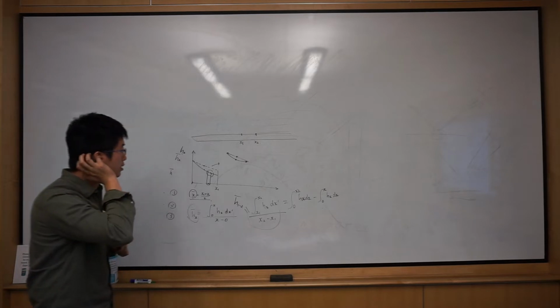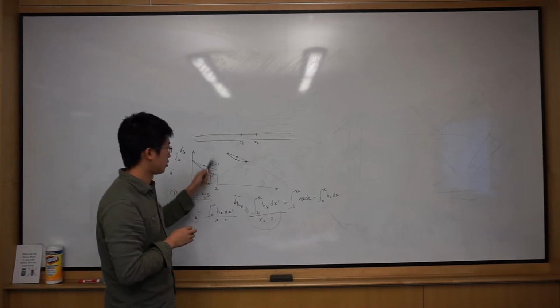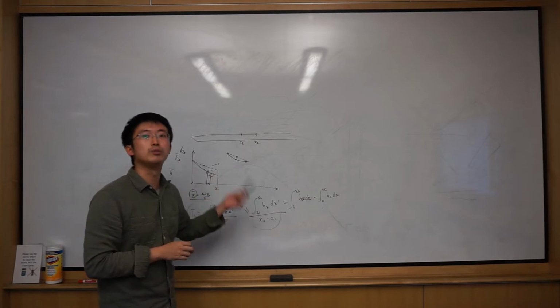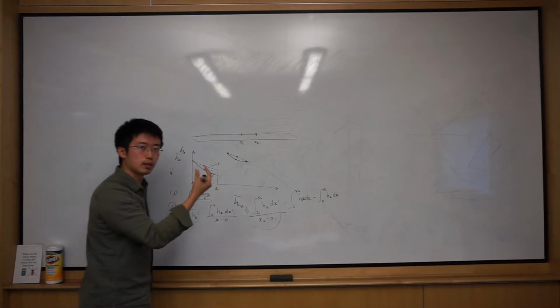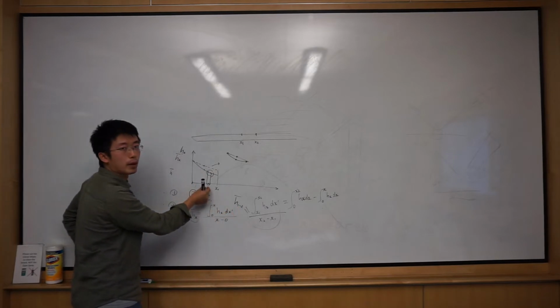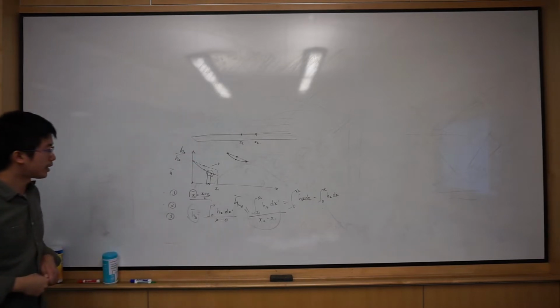So it only works if the convection coefficient function, the curve of this function, looks smooth. So basically, these 2 points have to be close enough and in the same zone, either both in laminar or both in turbulent. Okay.